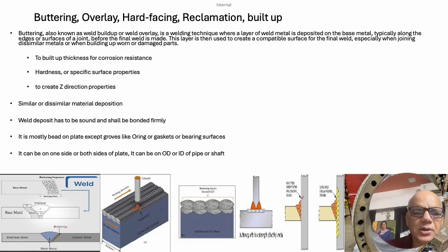So you dig away or take away some material from the parent metal which has Z directional low properties and deposit weld metal like shown here. So it is called a buttering or a layer to prevent the Z direction tear. It's kind of a build up, but there you deliberately remove material and build it up so that the weld is able to take in the Z direction the stresses which are going to come after you weld this vertical member or a beam.